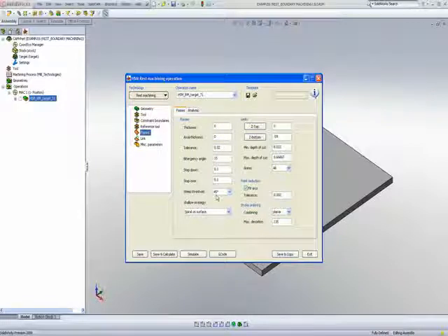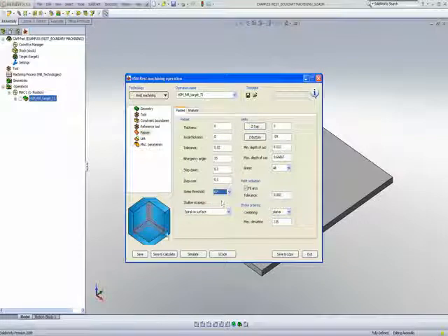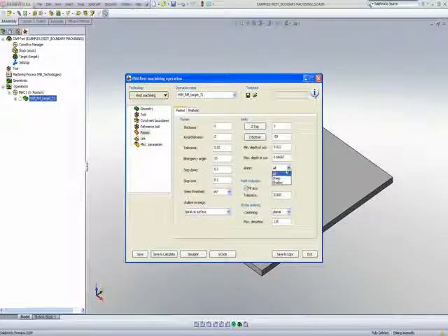And when I use my steep threshold of 45 degrees, it'll work on the shallow areas using a constant step over, and on the steep areas it will be using a constant Z. Now I have a filter that can say, only do the areas that are steep, or only do the areas that are shallow, or both together. This option is in this area called areas,